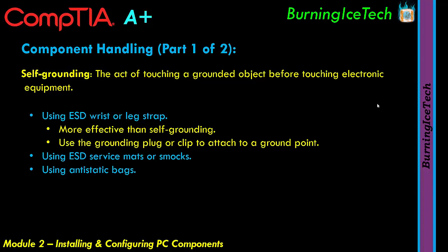And then lastly, using anti-static bags. Now that actually is something that you're going to use a lot. Whether you know it or not, you might have actually already used one, you just didn't know it. Especially if you go buy yourself new IT equipment. If you're going to buy a new motherboard, maybe new RAM chips, or any computer electrical components, you'll find that they quite often come in a very weird looking transparent bag. Quite often it looks like a silverish tinfoil kind of bag. It's very thick. That bag is actually an anti-static bag to prevent that component from being accidentally blown somewhere along the line, in the form of transport and all that.